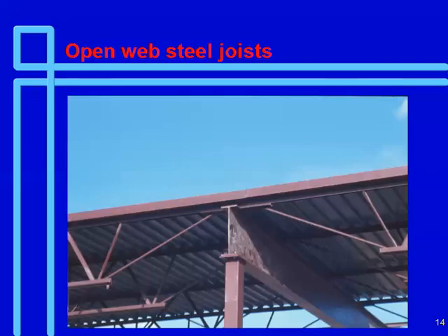Here's our joist. Here's a little HSS column and a beam sitting on top of the column. And you should all be going, oh my God, when you see that. Why should you be saying that? Because it's an unstable structure. More than likely, it's an unstable structure. You have to have a stiffener or stiffeners over here, or a joist extension or something to stabilize that column